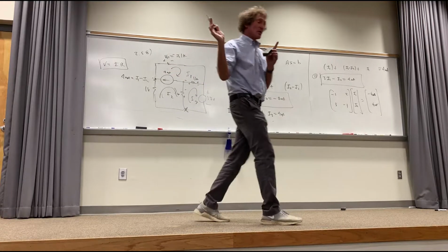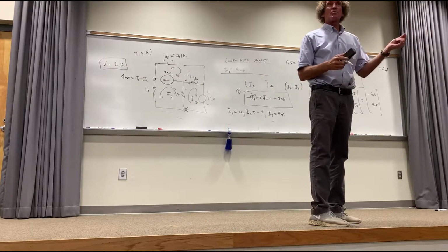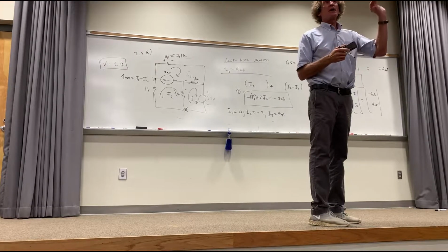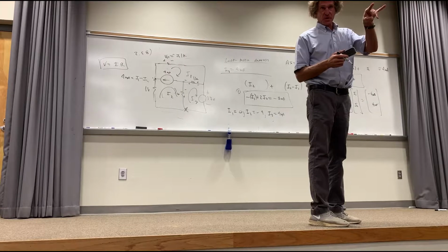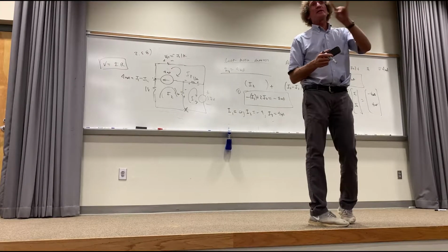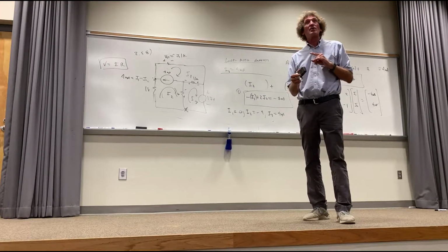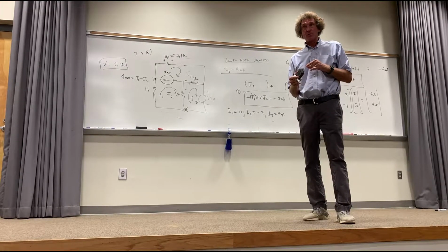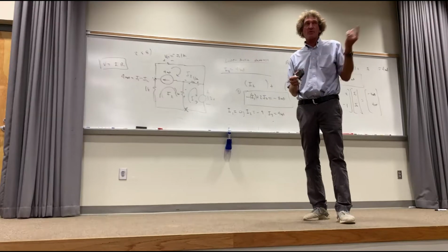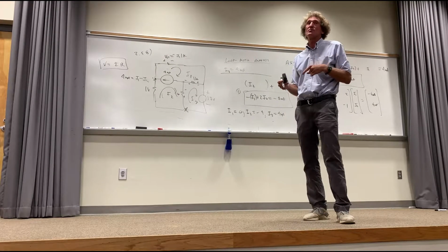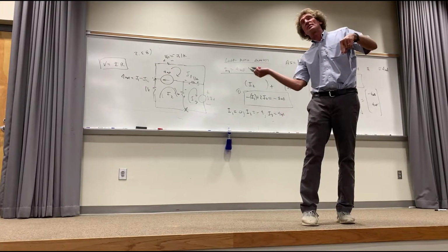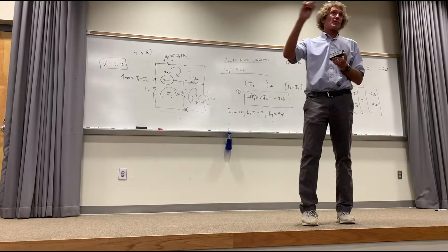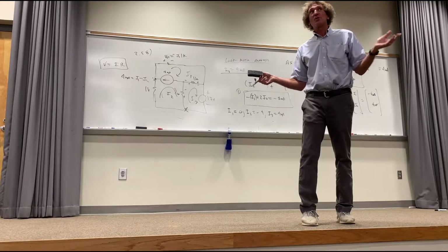Now, we've done nodal analysis, right? That's where basically for nodal we assign currents and then unknown voltages and we solve for the voltages, right? That was nodal. Now we did mesh or loop analysis. There we assign unknown currents and we solve for them by doing voltage drops around closed loops. The other one was Kirchhoff's current law. The sum of the currents into the node was 0, or the sum of the currents into equal to the sum of the currents out of. We'll solve for voltages. Here, the sum of the voltages around any closed loop was 0, and we solve for the currents.